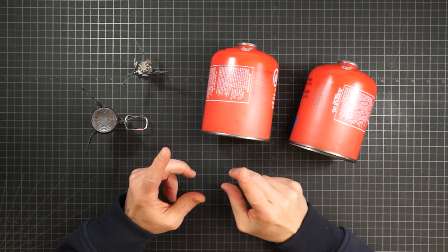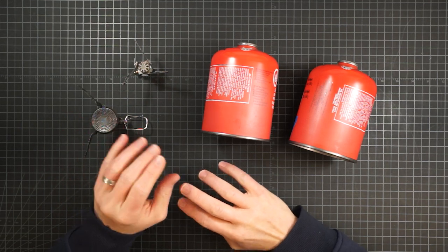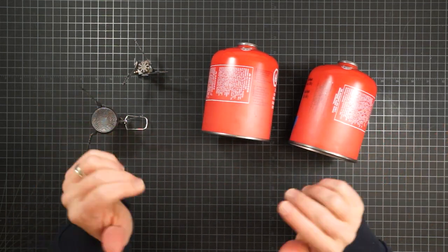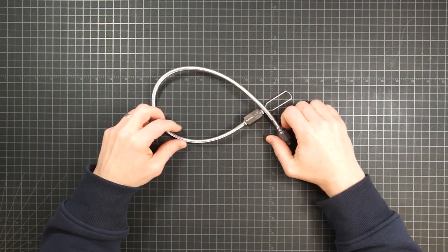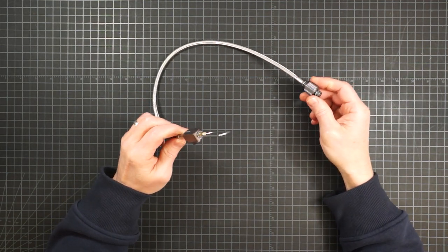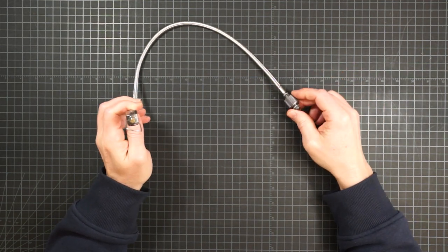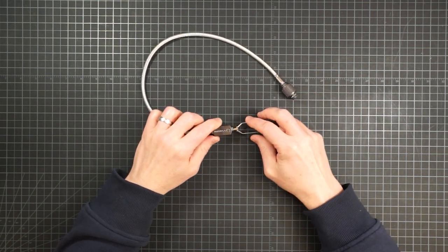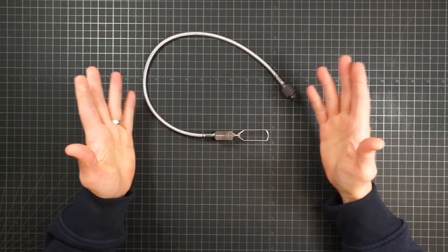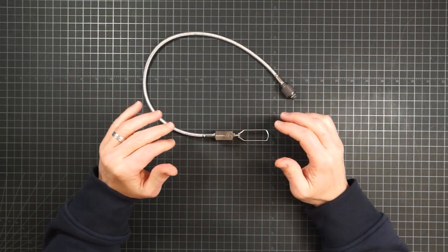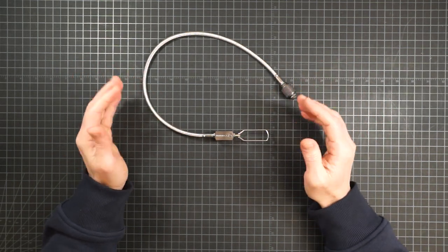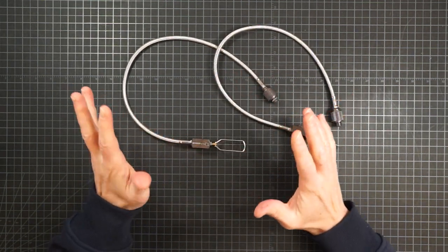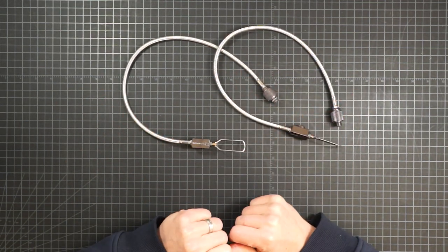Before touching my regulator, I ran more tests using 2 different stoves and 2 different gas canisters to make sure it wasn't some failure on those ends of the equipment chain. That left the extension hose I use to run from the can into the regulator. It's necessary for the additional valve. It occurred to me that something might have worn out or gotten clogged, thereby choking off the supply and preventing high from being high enough. Well, luckily I had a spare, but regardless of which hose I chose, the problem persisted.